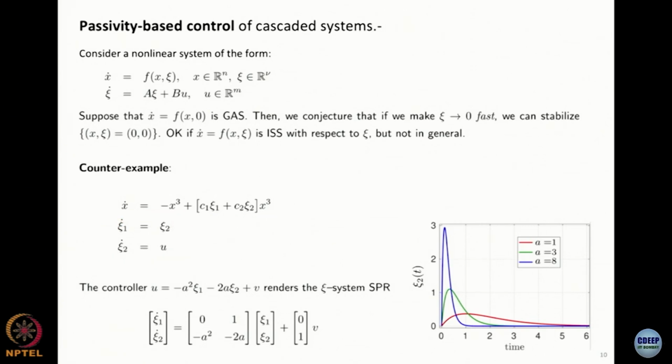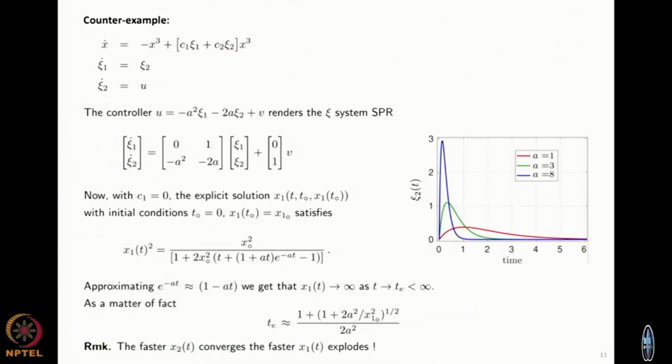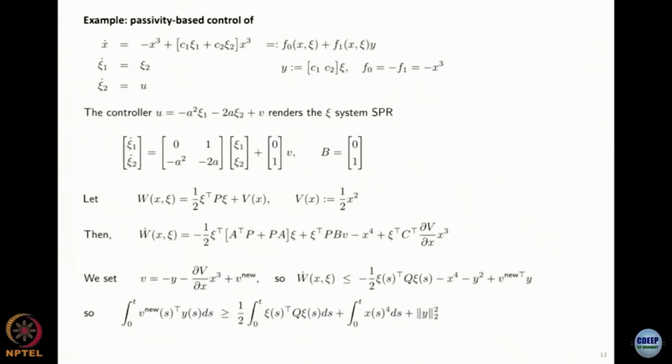So what you want to do is first design, well, I will skip this. What you want to do is to design U to stabilize psi, but not only do you want to stabilize psi, you also want to add an extra feedback to take care of these terms here. Okay. So according to the theorem I showed you, what you do is the following. First, if this is just a double integrator, you first use a feedback to put the poles of your linear system in the right place.